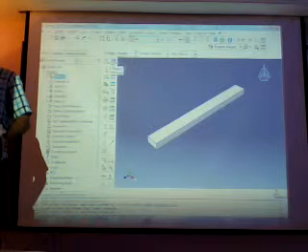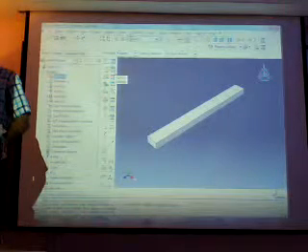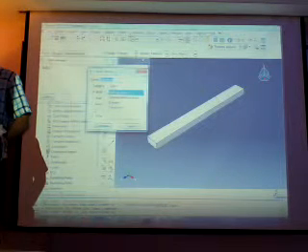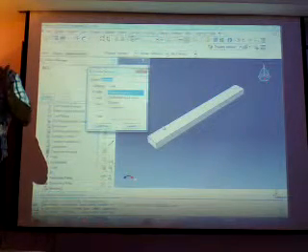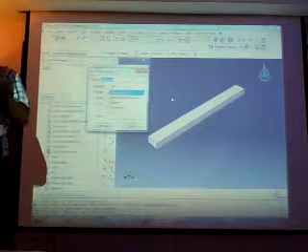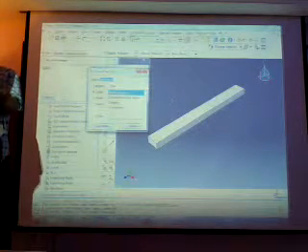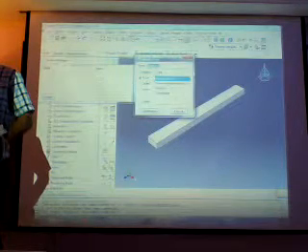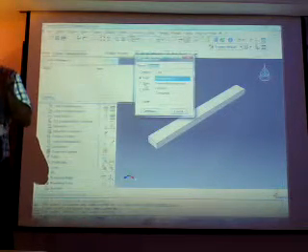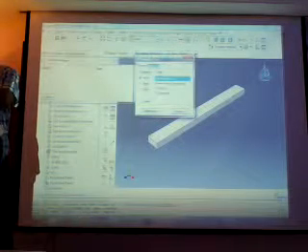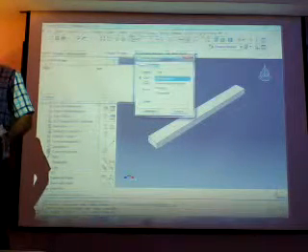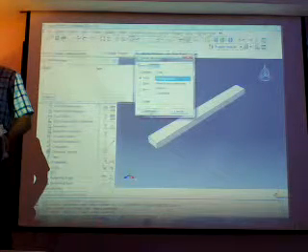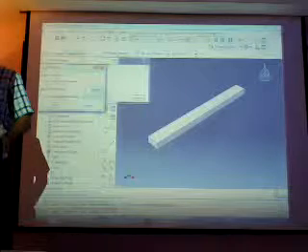After defining the material properties, we should define a section. Create, and we have different sections. In the part module, if you remember, I took a 3D solid. When your part is a 3D solid, here also you should take solid. Or if in the part module you define a shell, here you should take shell. Now we have solid, and we assume this one as homogeneous, and continue.